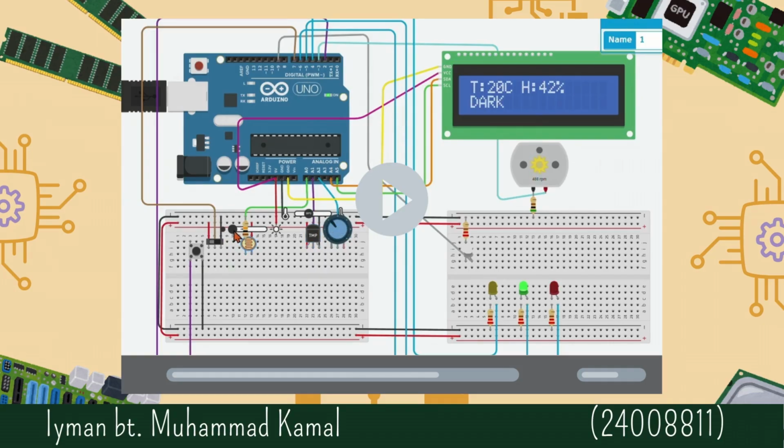The lighting system depends on the LDR sensor. When it is bright outside, the lighting system will switch back off. When the LDR senses it is dark outside, the lighting system will switch on. The user can toggle between the auto and the manual mode. To enter the manual mode, the button is pressed. Hence, the lighting system can be controlled by the user. By pressing the push button again, the system will re-enter automatic mode.